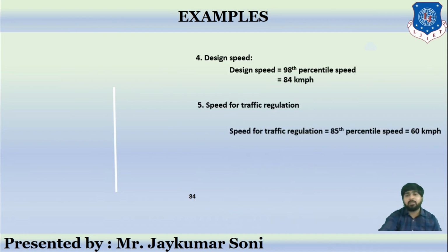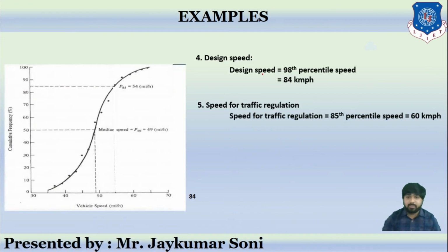Then comes the design speed. Design speed stands for the 98th percentile speed, that will be 84. You have to plot the graph like this. If you plot, you will get it like 84.